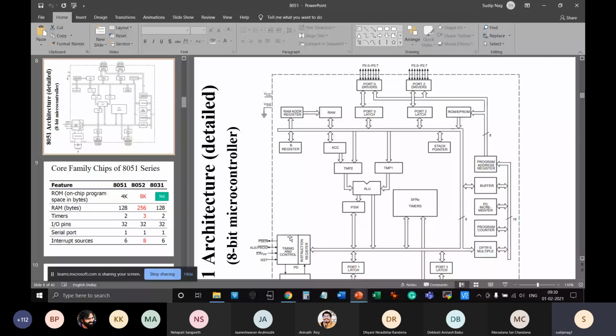Now, timing and control has read that through the instruction register. In fact, I'm giving a shortcut explanation. There are more steps, fetch, decode and execution, that happen on the other side, involving the program counter and so on. You fetch the ANL instruction opcode, and timing and control finds out that it has to activate the 8-bit ANDing circuit within the ALU. Once the ANDing is done, the result comes from the ALU.